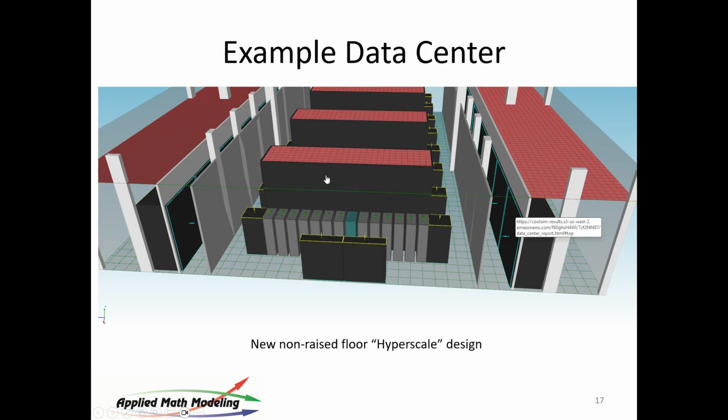This is hot aisle contained. So you see here this black box is around the hot side. The air is being blown from front here to back. Those are arrows, and you see it being pushed into the hot aisle. So it comes out of the fan wall and into the room. These are just diffusers to try to unify the flow a bit and slow it down. They come into the room, go into the servers, go into the hot, come up through the ceiling, back around, and make a circle. So in these designs, you have this situation where the air recirculates in a pattern that looks like this.